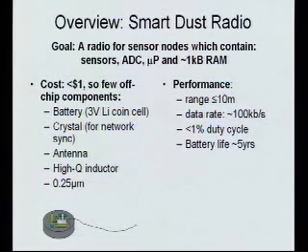So the idea of these things is they spend most of their time off with basically a clock running and nothing else. And then every once in a while, when the clock times out, they wake up, they sort of listen if there's anything they want to hear, they take some data, they send the data home, and they turn off again. So a low duty cycle, but a really long battery life. So something like 5 years. So you distribute them and you leave them until they're obsolete.